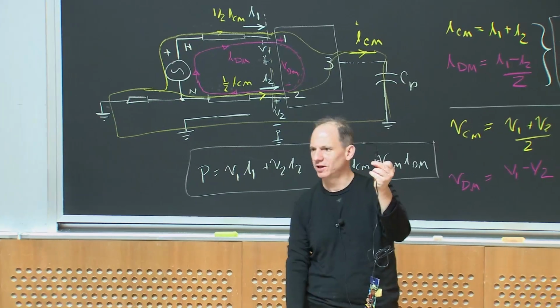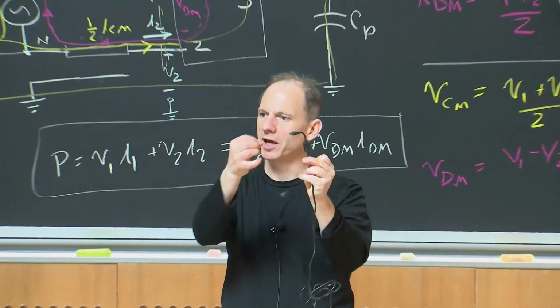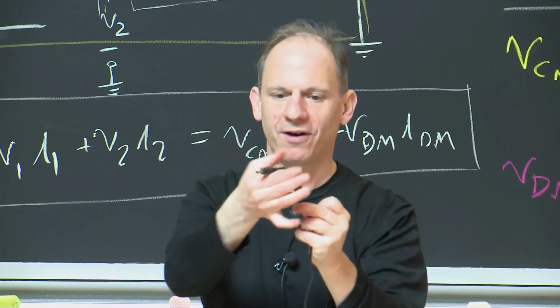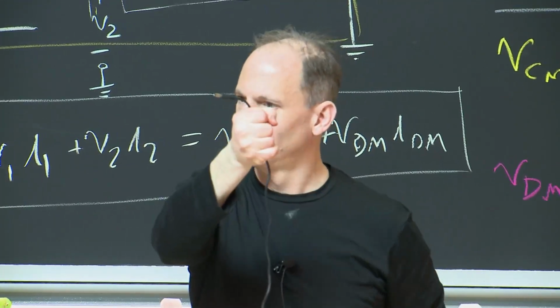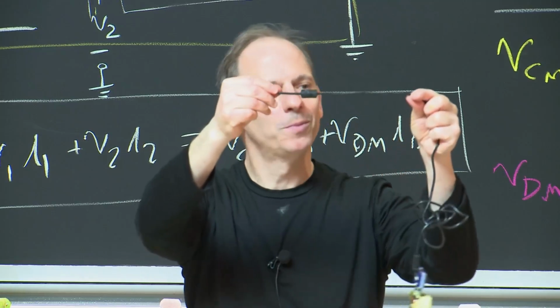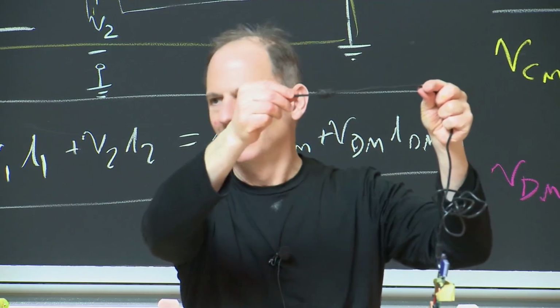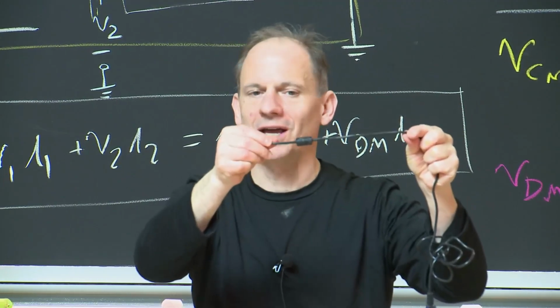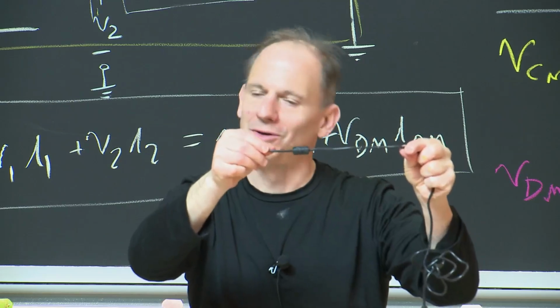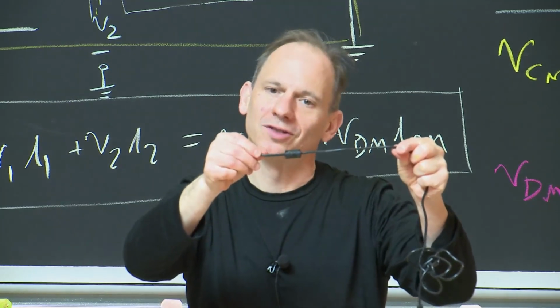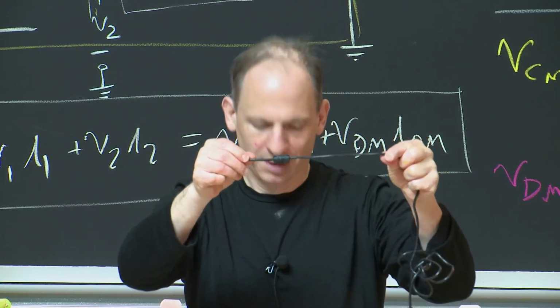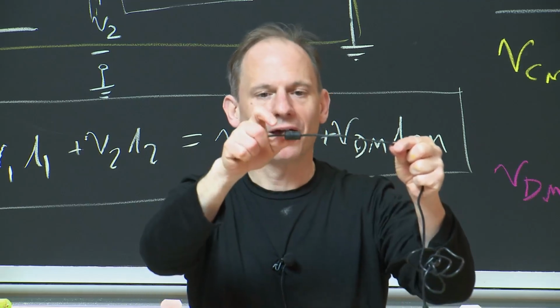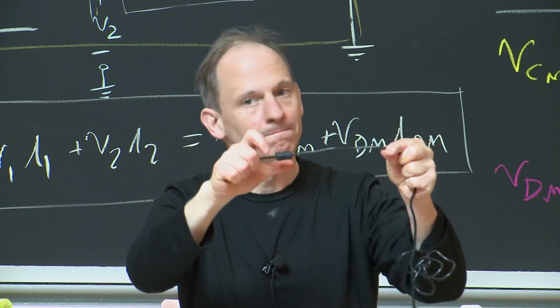All that cylinder is basically a toroidal ring of ferrite through which both leads are slipped. So this is just a one-turn common mode choke, right? It's helping keep common mode noise out, and it's very high impedance to common mode, gives you almost no impedance to differential mode. And that's why you can get a lot of filtering with a very small core.